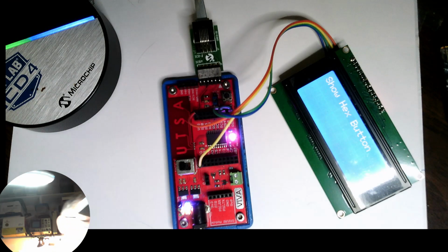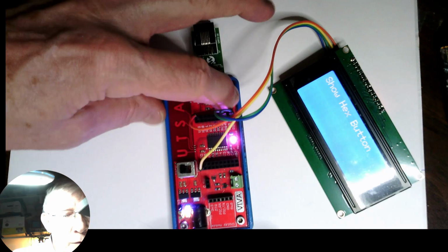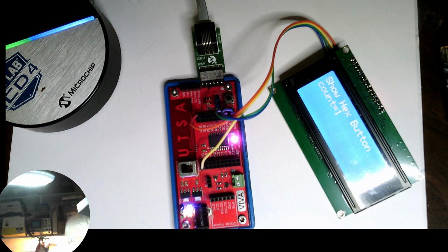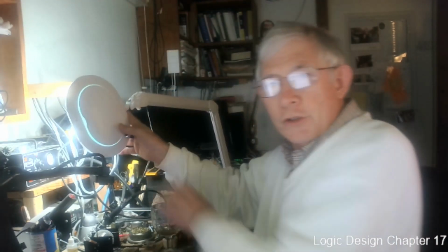Now we'll get this all set, and we'll go over here, and now let's see if we get rid of that problem. So we'll punch it. Oh, good. Yeah, perfect. 1. No problem at all. So that little delay fixed our little bouncing problem. And sometimes the bouncing problem's not too bad, but sometimes it can be kind of bad. So you can see a simple thing like reading a push button can become a little tricky.